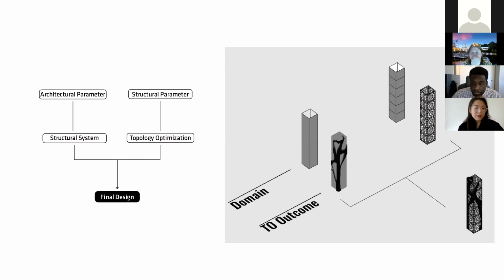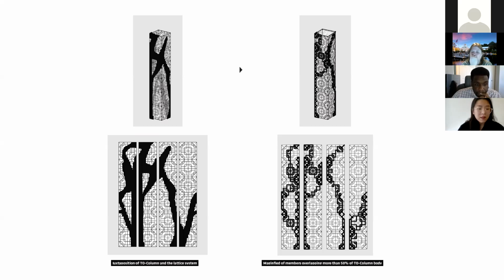And this is a combination process after executing the topology optimization on element form generation. The resultant TO forms were combined with the chosen structural system, which is the lattice discrete structure for this study. And since this pattern is not inherently structural, I introduced reinforcement to reduce the required loads, and it is some sort of sizing optimization. To accomplish this, the topology optimization form is used as a guide to reinforce the material along critical load paths within the member.